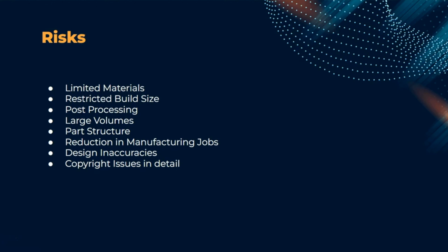Furthermore, printing is not always clean cut, meaning the product will need to be refurbished to get a smooth finish and remove the excess support materials. This is done many ways, including water jetting, sanding, chemical soak and rinse, or air heat drying. This further limits the overall production speed of 3D printing and increases production costs.